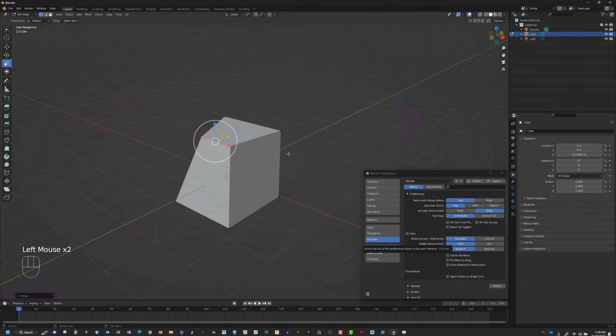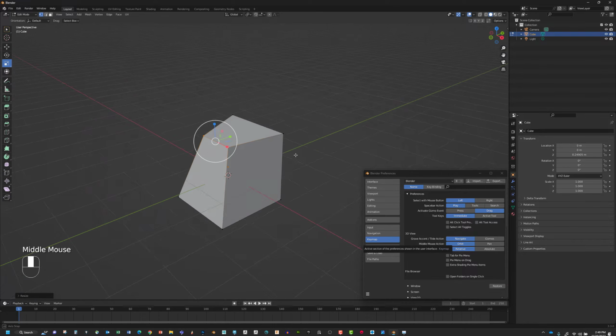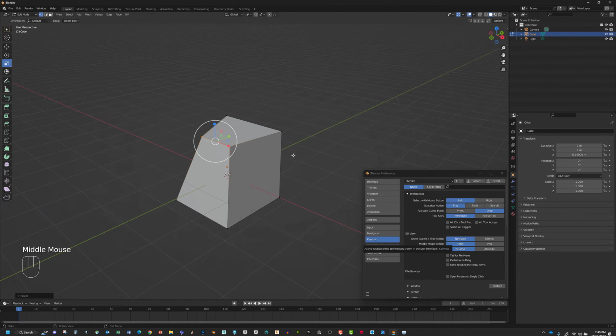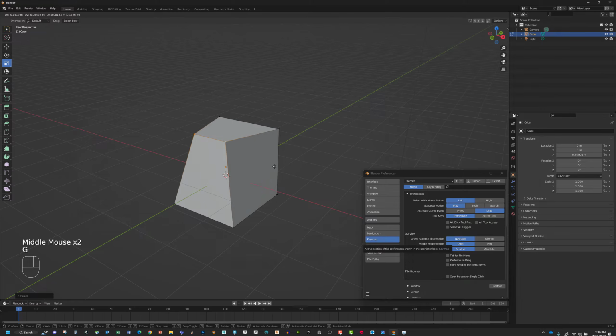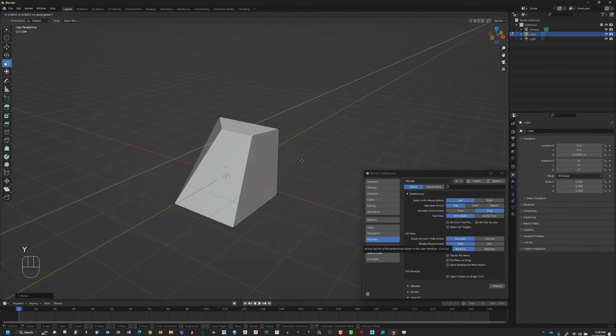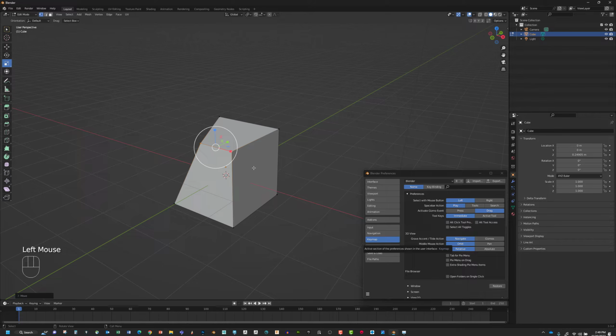So if you remember all the hotkeys that we talked about for the Blender setup, those are all going to be valid for you. If you tap G, that's going to move, and again we can move this on Y, we can do Z, we can do X, and if you're happy with the setting on that, you can just click and you're good to go. So that's going to give you these different settings for that.